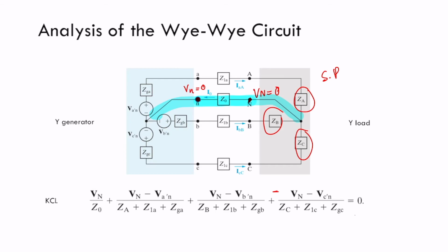Loads can vary a little bit, but the variation can be very small. So typically this neutral cable exists, but in general it is a very small, very thin cable because it is just to compensate any unbalanced condition. Here, we are not going to deal with the unbalanced system, but there are some equations to deal with that.